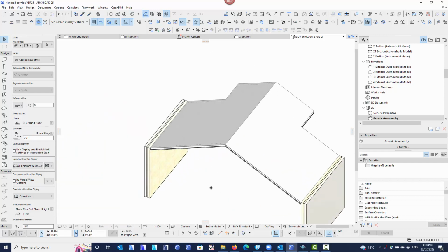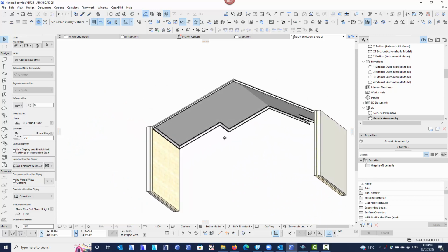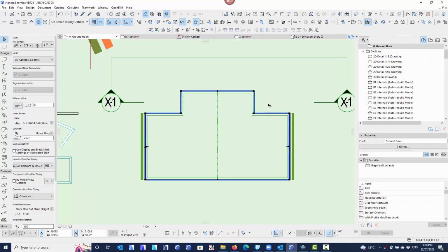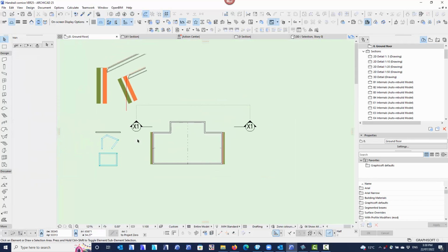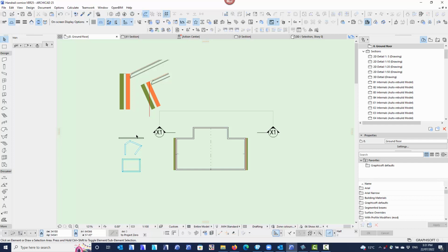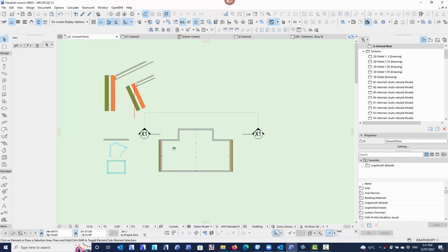So it takes a little bit of getting used to, a little bit of experimenting, but you can see you've got quite a nice raking ceiling. So the railing tool is actually quite handy for raking ceilings as well. So our options are the old cornice, single cornice where you place on each edge of the ceiling, adjust the rake angles, adjust the rolls, adjust the mitres, or the beam tool, which is a little bit quicker in that it does the corner mitres and stuff for you automatically. We just need to drag it across to match the wall when we change the roll angle. Or the railing tool, which is quite a handy one to do as well.